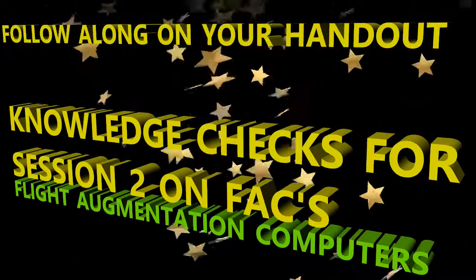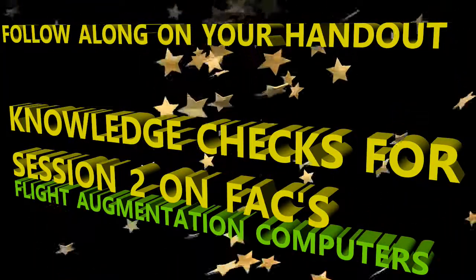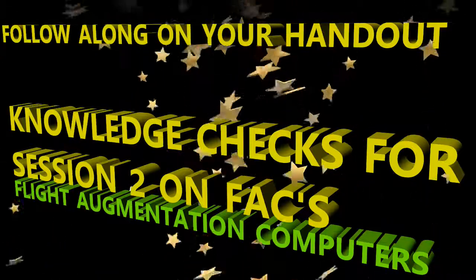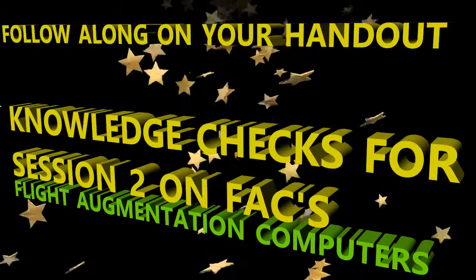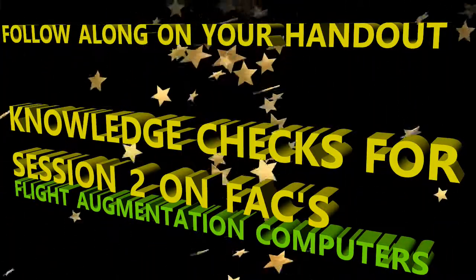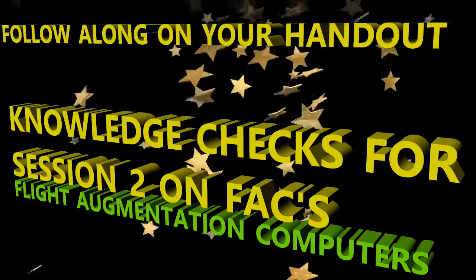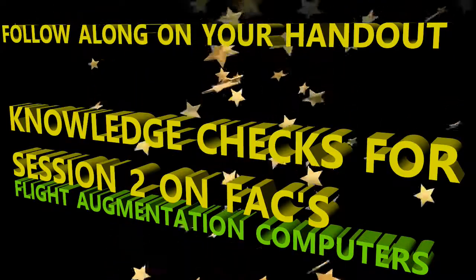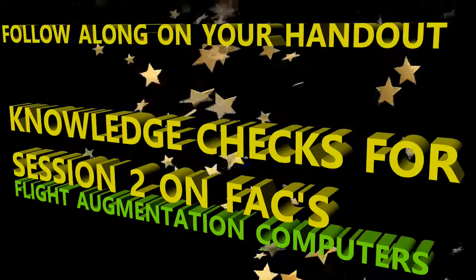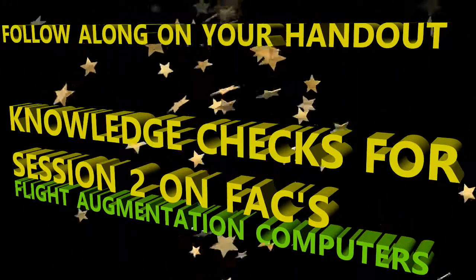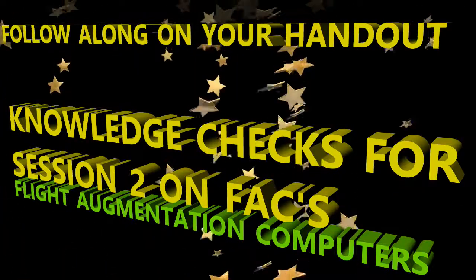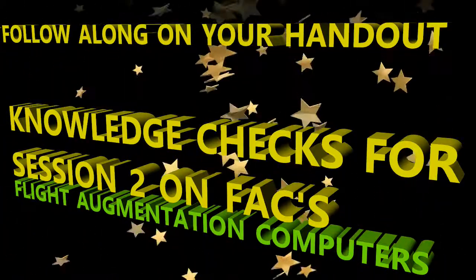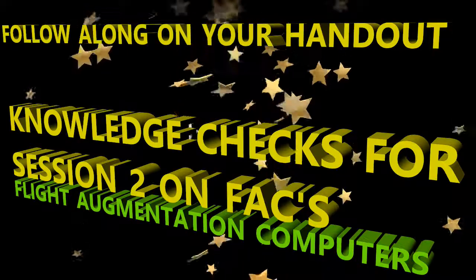The AFS is a fail operative system. What does this mean? Okay, your two choices. It means that right after failure of a single system component, the plane can achieve a successful ILS approach, auto land, and rollout? Or does it mean that right after failure, there's no significant change of attitude of the aircraft or the flight plan? Okay, the answer is the first one.